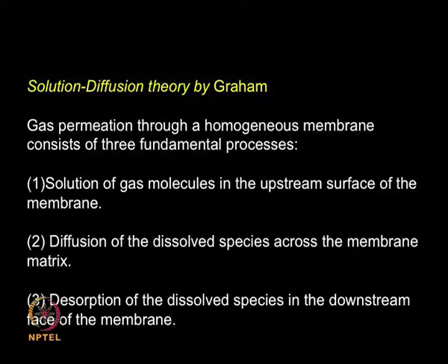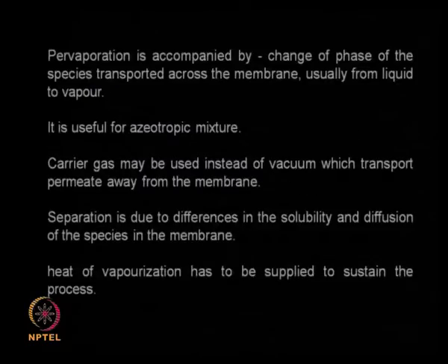So you are going to have the gas molecules going into solution in the membrane, diffusion of the gas molecules through the membrane, and finally the desorption of this dissolved species back into the vapor phase. So all these parameters affect this pervaporation process, and that is what Graham has proposed, and that is why he calls it the solution diffusion theory.